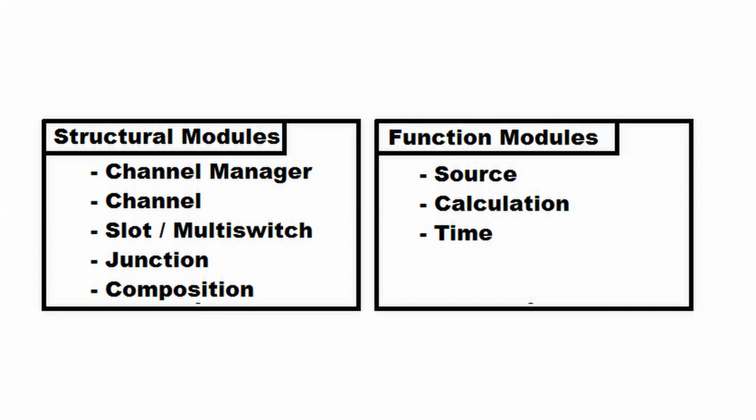A calculation is modules which, for example, when you have a signal from the stick and you apply some kind of gain to define the motion range of the servo or the speed limitation of the speed controller. So a gain module would be a calculation.